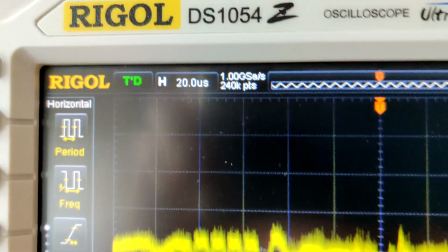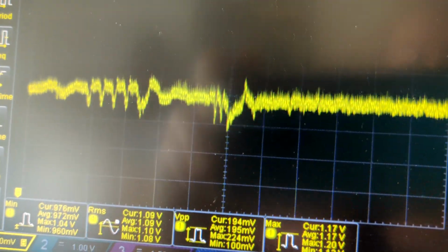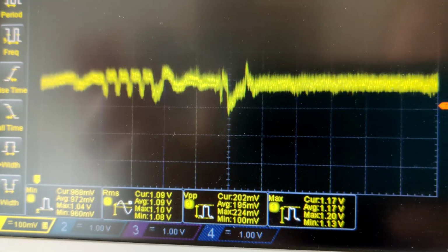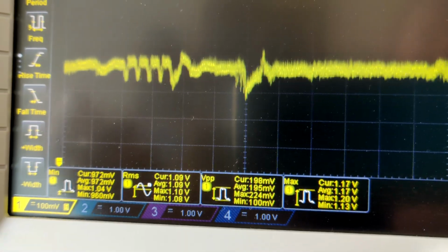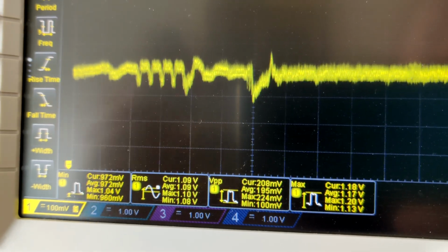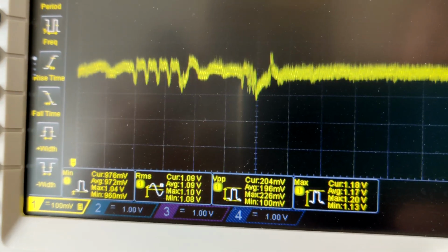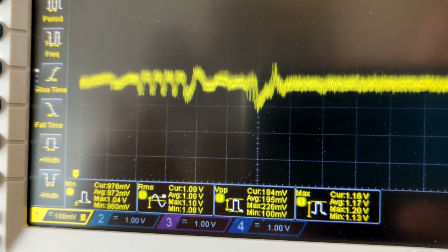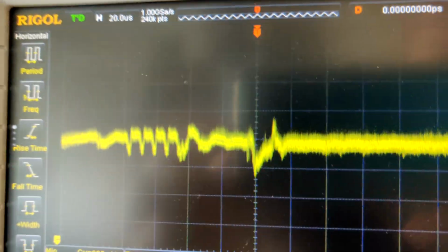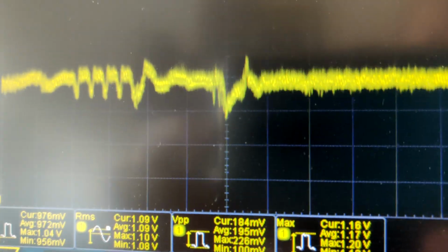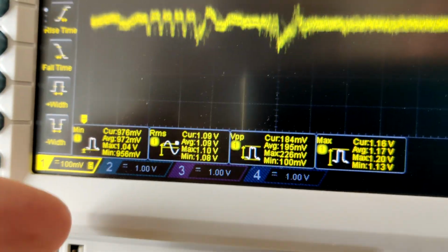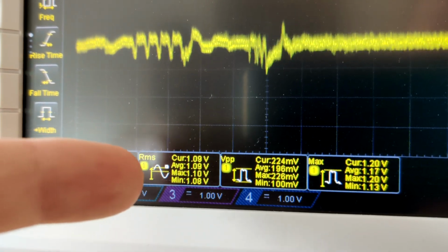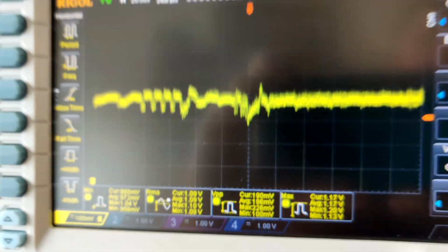This is not that much. You can see this is only 20 microseconds per division, so every square is 20 microseconds, but that's long enough. Even this old GTX 480 is running at 750 megahertz. That is 756 million cycles a second. So that's quite quick. That is a lot quicker than those couple microseconds, and many clock cycles happen while the voltage is that low. So our overclocking is represented by this number, whereas our power draw and heat output is represented by this number.